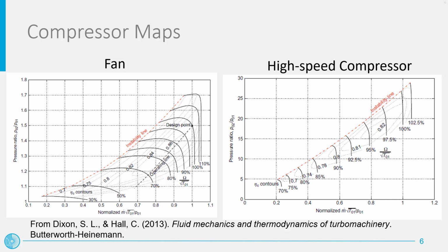Compressor maps in the form they are shown in the slide have two main drawbacks for system simulation. First of all, the isospeed lines do not cover the same range of pressure ratio and flow coefficient. Keep in mind that the flow characteristics need to be coded in the model as a matrix to allow for a numerical interpolation. If the rows and columns of this matrix represent a given value of the flow coefficient and the reduced speed, or even the pressure ratio, many elements of the matrix will end up having a not a number value.